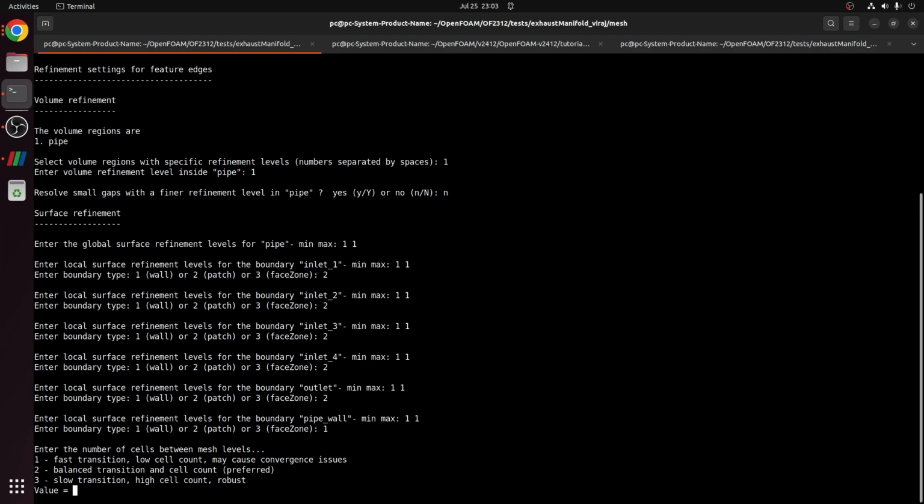From that fine refinement level to the next, slightly coarser refinement level, whether it wants to go faster or slower, in the sense of how many cells you should have in between. Because in CONVERGE a larger cell can be connected with the next level, since CONVERGE allows hanging nodes. snappyHexMesh doesn't do hanging nodes, and OpenFOAM also doesn't allow hanging nodes.